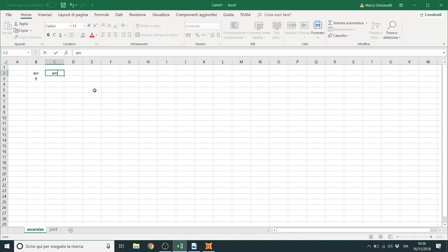So the amplification will be the critical load divided by the critical load minus 1, which is 1.12. So the first order displacement is 35.8. I expect the second order displacement to be more or less, because it's a simplified approach, 40.3.